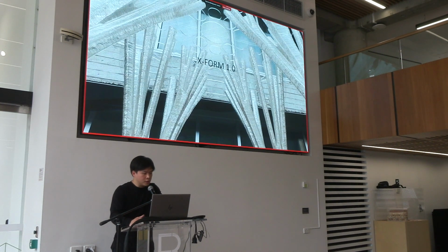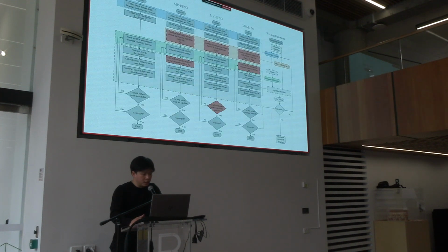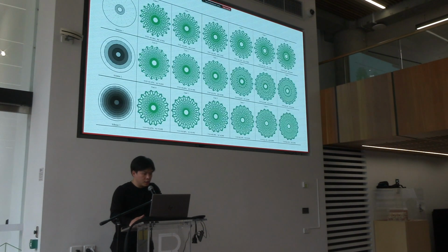The XFORM 1.0 is a project we did in Shanghai 6 years ago. We developed our BESO method, which is oriented for architecture design. Because we change different data, we try to make diverse results for topology optimization. So you can see if we enter the same loading and same boundary conditions, it can create different results, which gives more diversity for the designer to use.